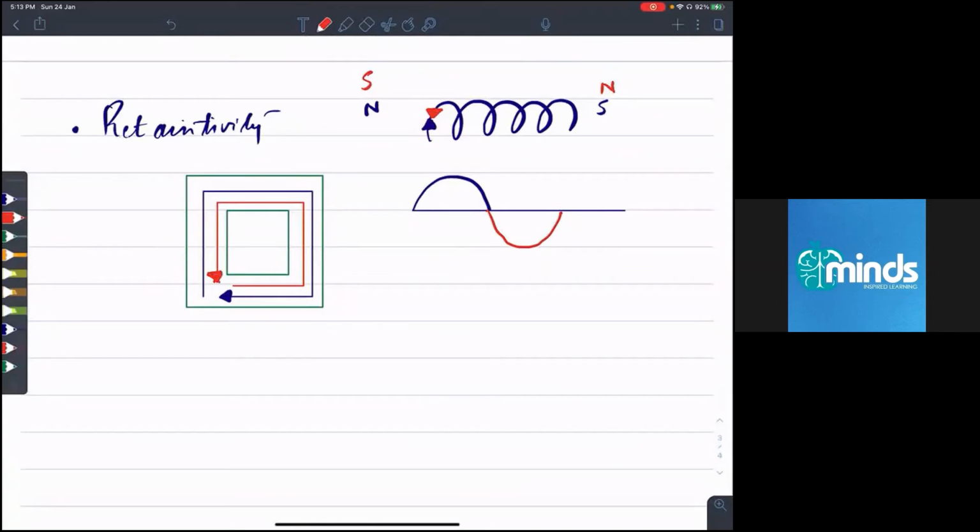Actually, if you focus, directions are opposite of each other, because here this direction is upward and here this direction is downward. Are you people getting it? When magnetic lines of force are passing through the core of the transformer, when alternating current changes the polarity, the direction of flow of flux should reverse, right? But what if the retentivity of this core is very high? It will take a lot of effort to change the direction of magnetic field. Is it making sense now?